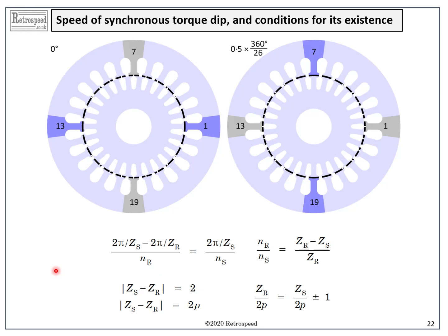All of this is very complicated, and I would say it explains why there is so much advanced analysis, even for inverter-fed motors, which do not always have to run up from standstill on the line frequency, but are always operating at low slip, apparently far away from any dips. But for inverter-fed motors, there's another complication, which is the effect of time harmonics in the current and voltage waveforms. Time harmonics. Aren't all harmonics time harmonics?